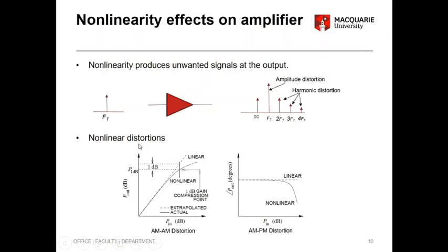One of the specs that you give them is P1 dB, right? So even if you get a totally unfamiliar circuit, if you know the P1 dB, you sort of get an idea: okay, this is the limit. You can't go beyond that. So one measure that you actually provide is P1 dB. Now I'll try to explain it as simply as I can.